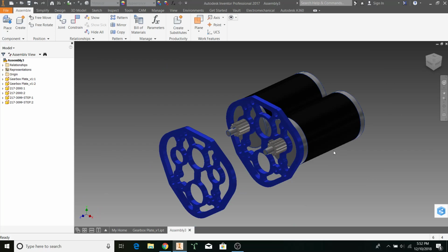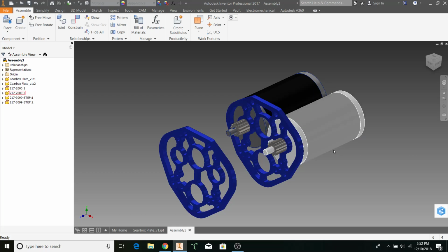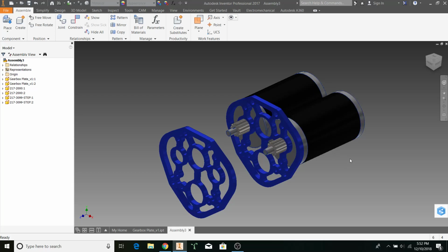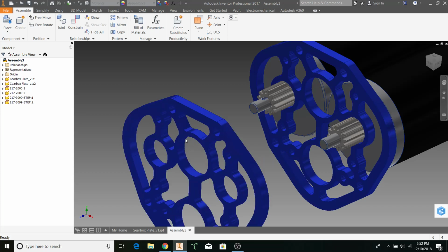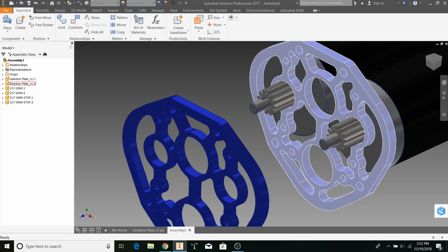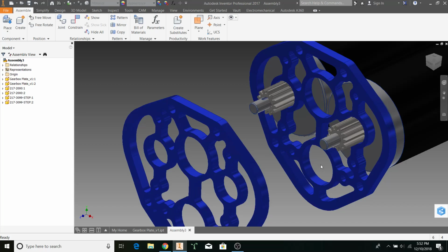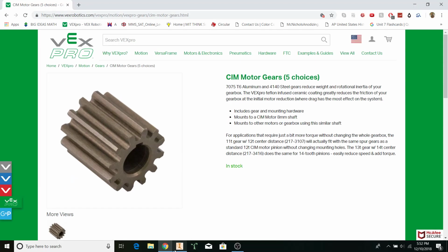The next thing we want to do is, I'll be skipping over the rest of the gears, and for now I want to import the bearings. The bearings are really important because it helps us align things up really quickly once they're in. In typical gearboxes, you'll see round bearings on the top hole here, the back hole here, and the bottom hole here. The reason that we use round bearings is so we don't have to use E-clips on our gearboxes. Round bearings, you'll notice, have an inner diameter of 0.5 typically.